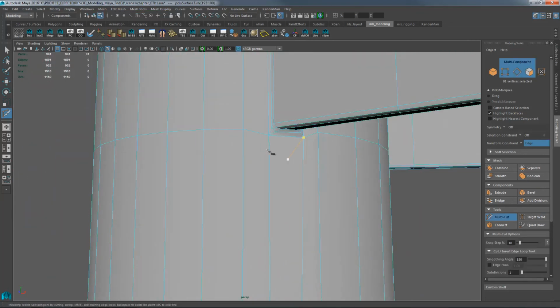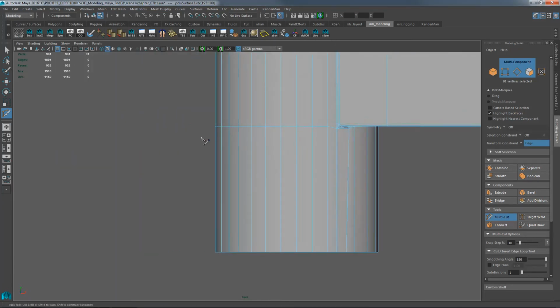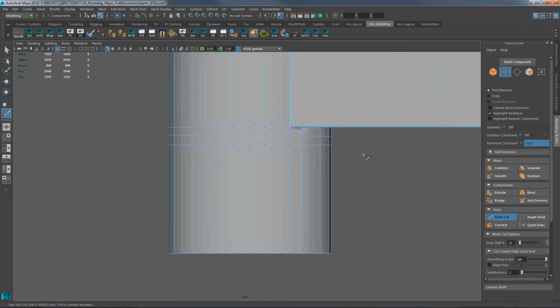We could use immediately an edge loop support across the bottom. And I think doing that as a straight line. So I'm going to multi-cut, holding shift, and just add that as a straight line. And then tag that and just tuck it in closer as a supporting edge loop. I guess let's do that one more time. Closer. Yeah, okay. That should do it.